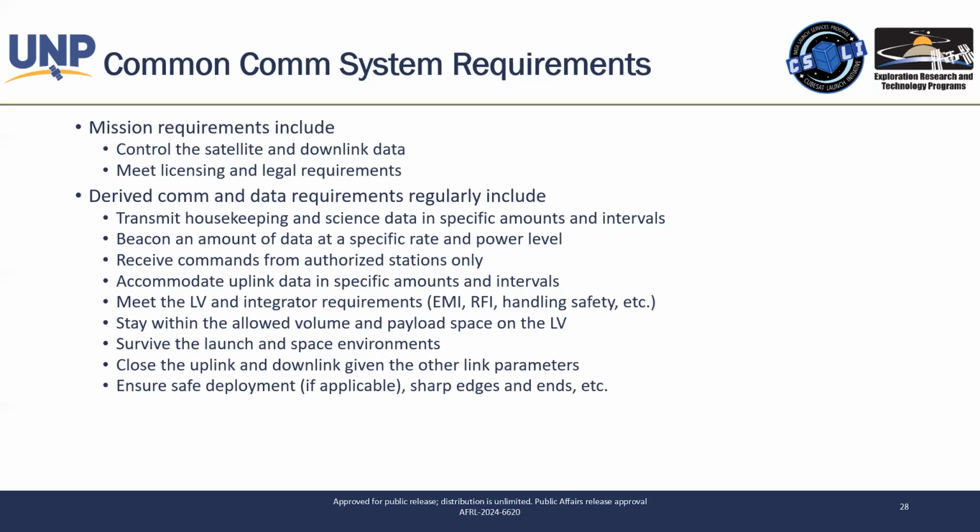Obviously, we talked about meeting licensing and legal requirements. Some of the COMM data requirements that we care about, some of the things your satellite may do, they may transmit housekeeping and science data. They may beacon. A beacon is essentially like a heartbeat saying, hey, I'm still alive, here's my status. It's something it may do that you need to take into account because it will have an impact on your data budget.